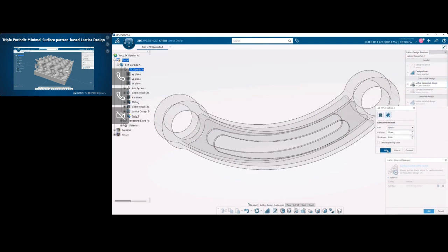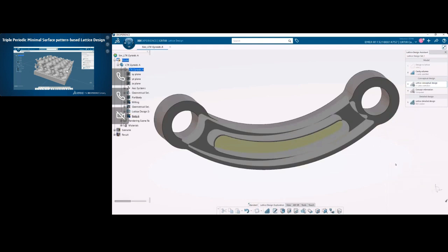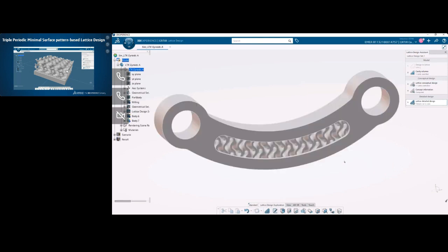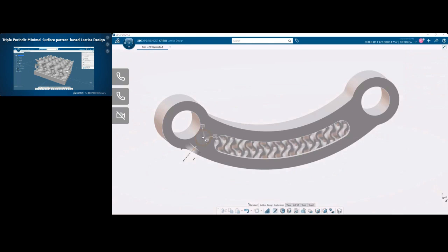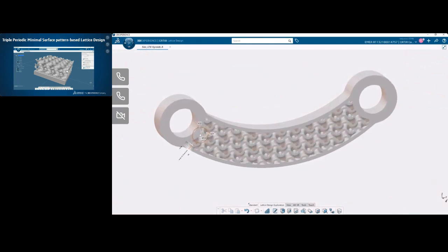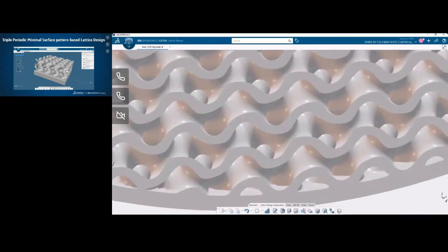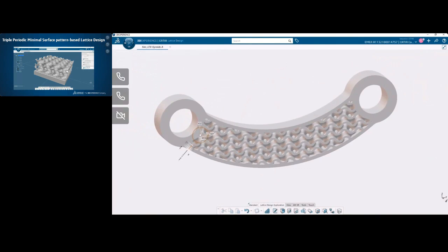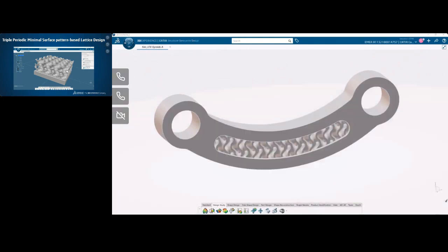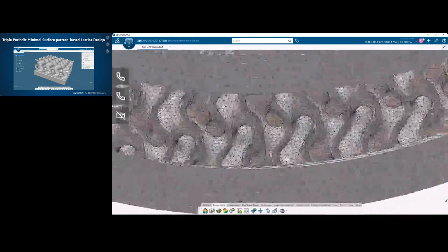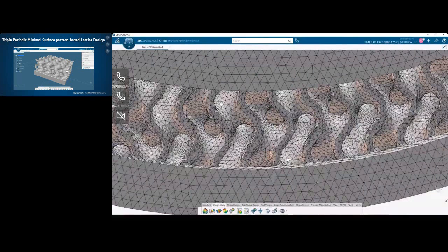But before actually printing the part, we would like to run a simulation. And in this particular case, we'll not use the light representation. We'll use the tessellated representation because we want to run a simulation which cannot be used by an idealized finite element like a beam. Okay? So we really want to mesh everything. So here we use a tetrahedral mesh for the whole part. It can be, of course, small elements because the lattices are very small, but you can do it.